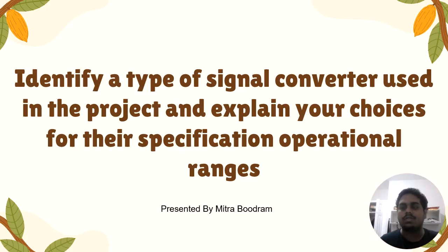can't read RS-232 directly. The torque sensor outputs a low-level millivolt to volt strain gauge signal, so we use an HBM conditioner like a ClipX or a PMX to convert it into a standard 4 to 20 milliamp signal. For the PLC, all other transmitters, temperatures, levels, and flow are already provided in the range of 4 to 20 milliamp outputs, so they connect straight to the PLC with no extra conditioning.